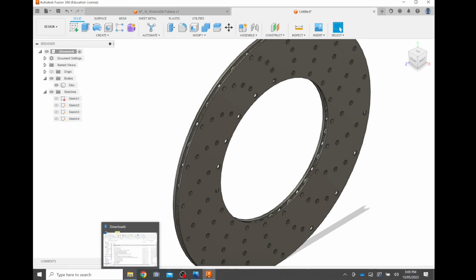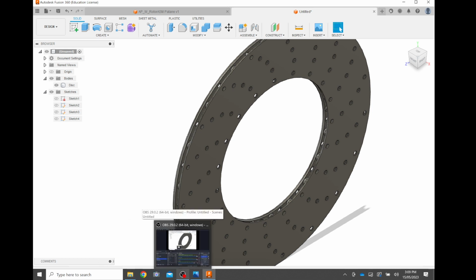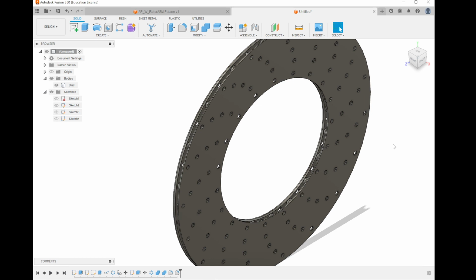Well, could you fillet it and then do the pattern? Like, so you fillet one thing and then you pattern it around it? Yes. The only issue is then you'd have to cut it, because I think for it to be filleted, it has to be one solid part. So you can do that. You can do it once, and then there's a way you can slice a piece off and then copy it and make it into a circle.